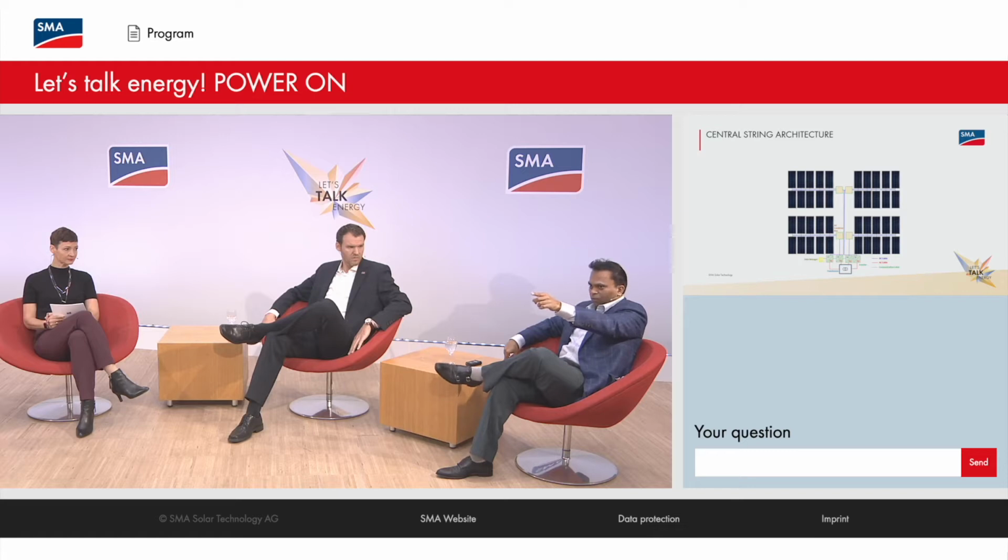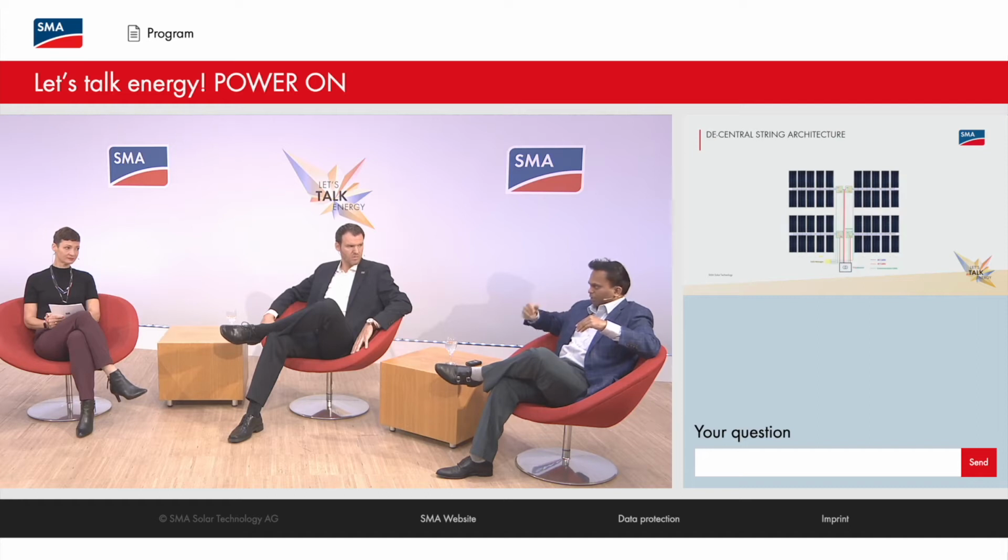These inverters are these 4 boxes sitting under the panels, and there the direct current gets converted into alternating current, and then that gets sent to the transformer, which is at the very bottom. The 4 inverters close to the transformer are what make it a string as well as central architecture. So it has the best of both worlds, so to say. It has the string architecture on the AC side and the central architecture on the DC side. Also, you see that the communication cables are very short, and they are closer to the grid. And this is the central string architecture.